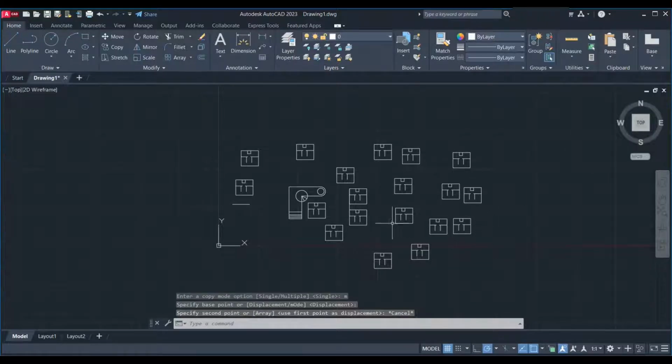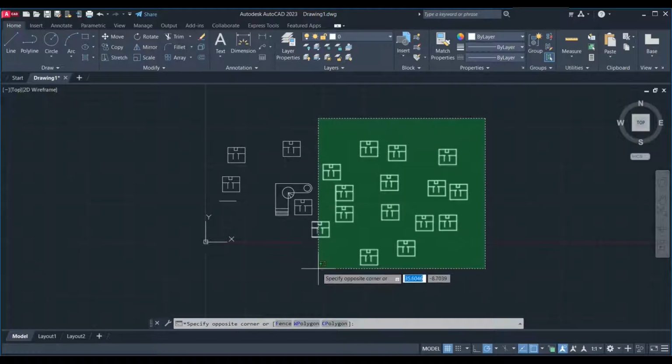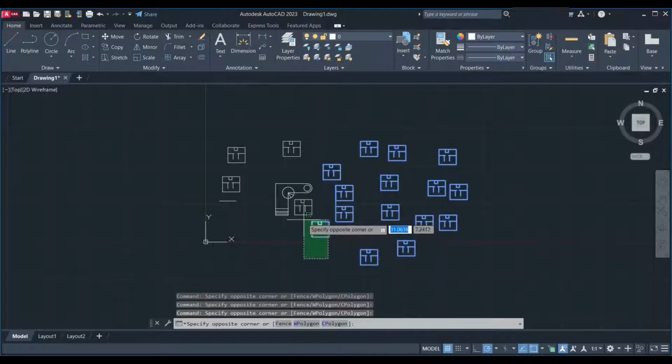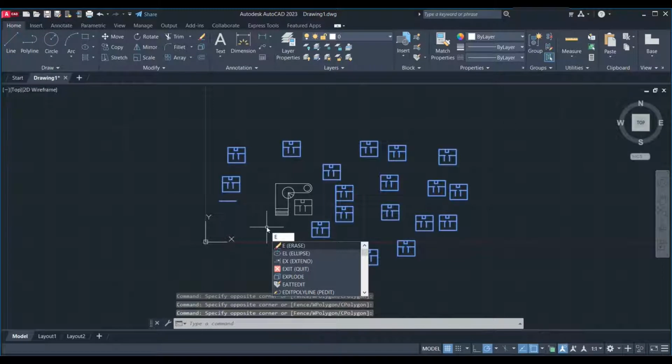Guys, let me get rid of these drawings. I wanna point out one thing. If I didn't know about the selection window, I would have to click on the objects one by one to select them. Now I easily create a selection window, another one, and also here, and this one. Press delete or type E, press space or enter. No difference. I think the space key is more handy. Well.